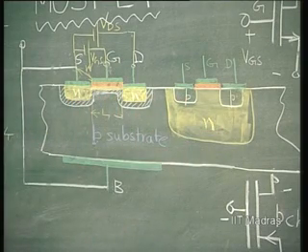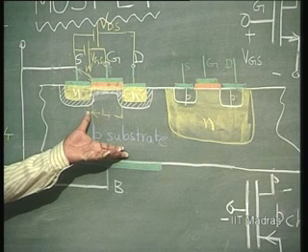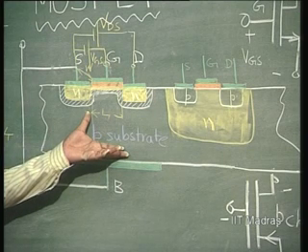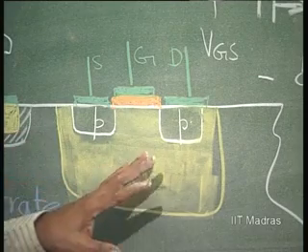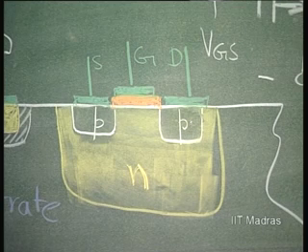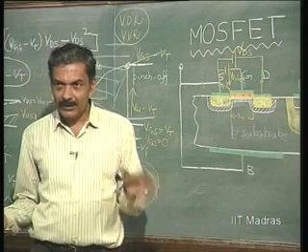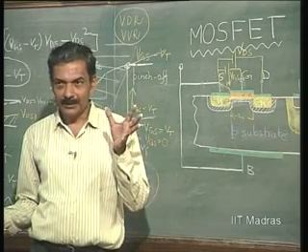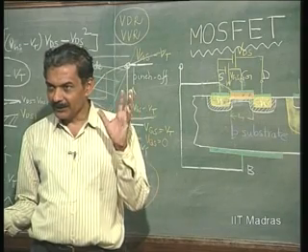This is called CMOS, complementary MOS. This technology of fabrication is called CMOS technology. You can have a technology where we do not have the P-channel at all, we have only N-channel MOSFETs throughout. So, you can have N-channel VLSIs or P-channel VLSIs or CMOS VLSIs. These are the three different technologies available for fabrication of very large scale integrated circuits.